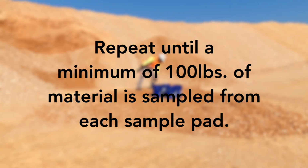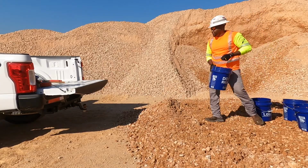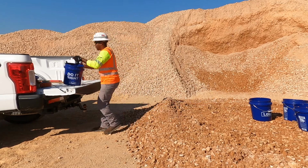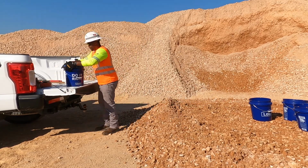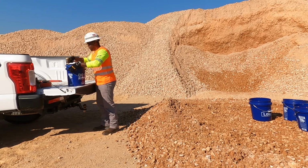Repeat until a minimum of 100 pounds of material is sampled from each pad. Seal and label the sample bags or containers and properly secure for transportation to avoid any loss of material.